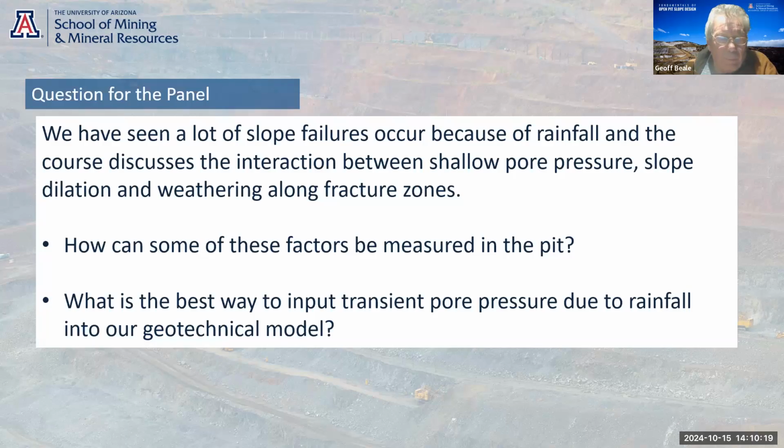So holes with closely spaced piezometers, horizontal drains which aren't too deep and which target the dilated zones, and horizontal piezometers and TDRs.